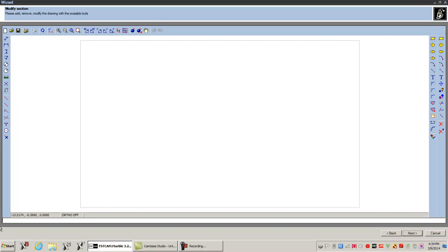So what I'm going to do is make a rectangle. Many ways to make a rectangle. You can make 4 lines. You could type in coordinates. Many ways. So I'm going to pick rectangle. And down here it's asking me for the first corner. I'm just going to type in 0, 0. Alright, my other corner is 60, 30. Done. So that's all I want, a basic rectangle.